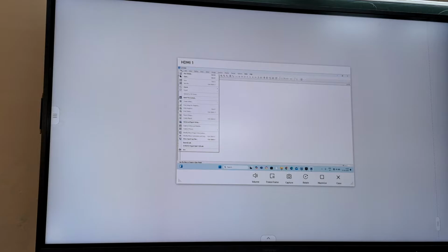Like if you want to simulate customized member behavior, there SAP 2000 is better compared to Etabs. We'll see what the difference is with respect to a section. If you have a section given and the reinforcements are specified, how to calculate the moment curvature of that section, you are already studying that, with respect to confined or unconfined. Now we'll see in the software what the difference is between Etabs and SAP. First we'll try in SAP, after that we'll go to Etabs.